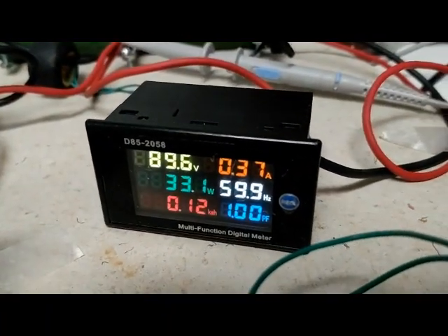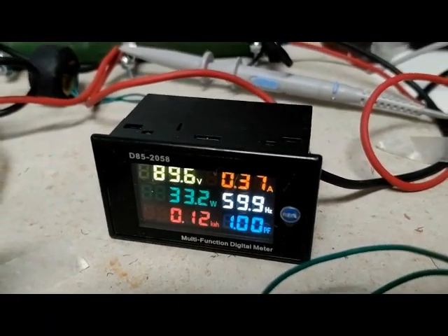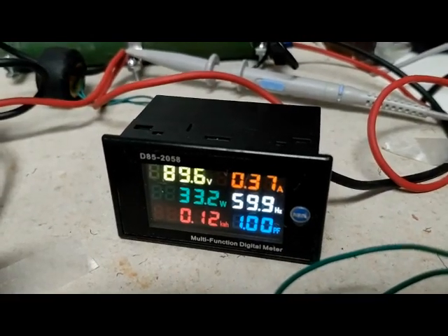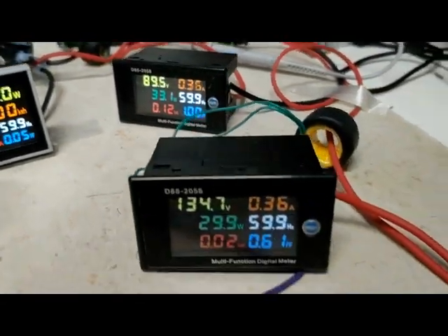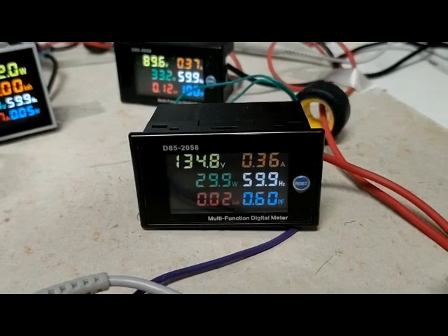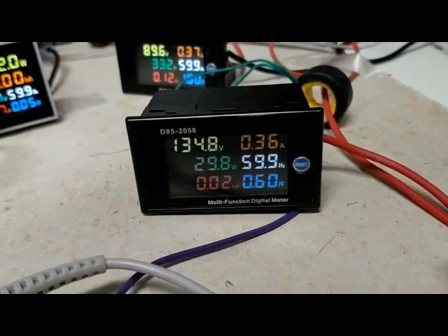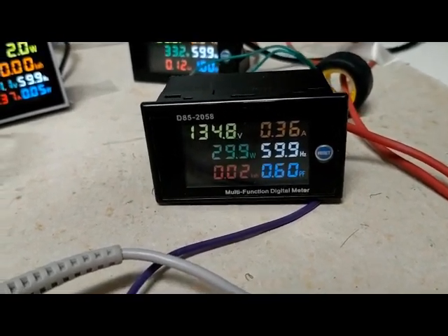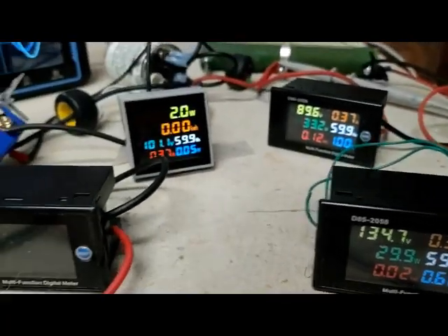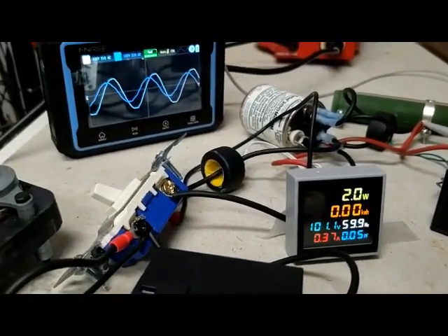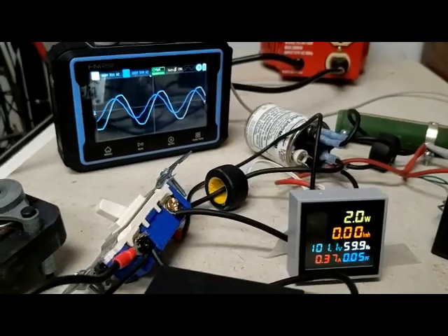If we look at the capacitor voltage, it's getting 101, and the power factor is terrible. And the resistor now is almost 90 volts. The power factor is still 1. The power factor for the overall circuit has gone down to 0.6. Now what happens if I bring the motor back in while leaving the capacitor in the circuit?